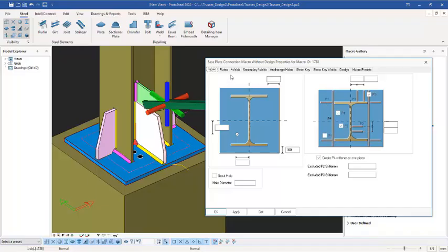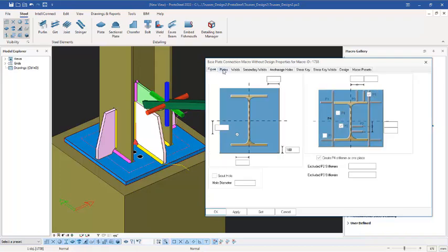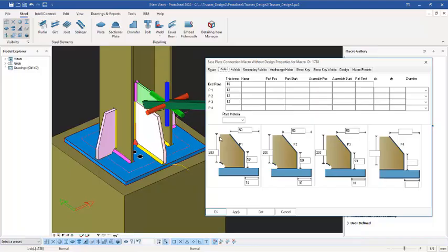So if you get to the plate itself, you can see here we have the thickness of this plate to be 16 millimeters. So the thickness of P1 is 12. Up to P3 we only have P4 because we have removed it here. Alright, so go back to these provisions. So the height of the stiffener, you can see the height of this stiffener now is 200 millimeters.